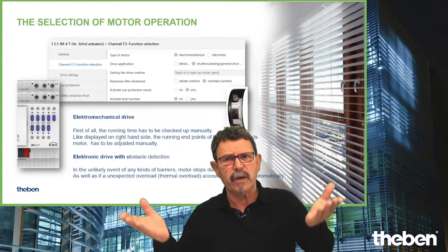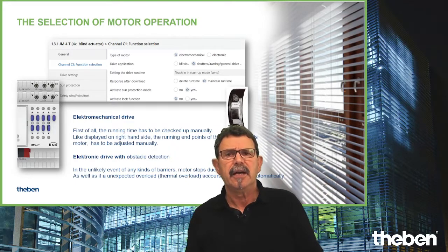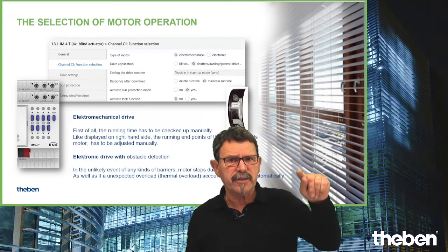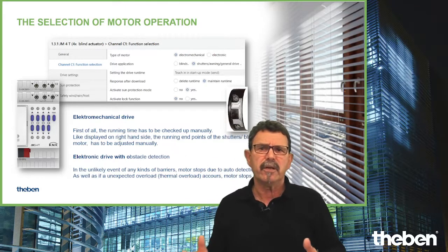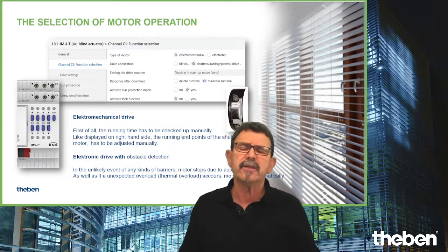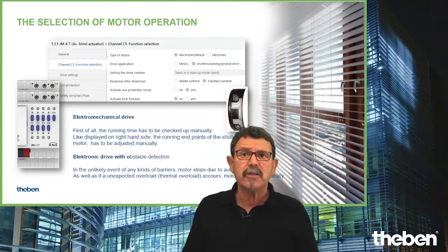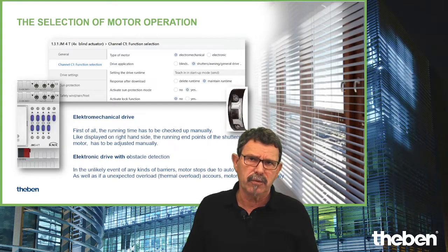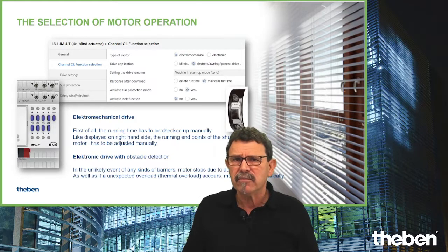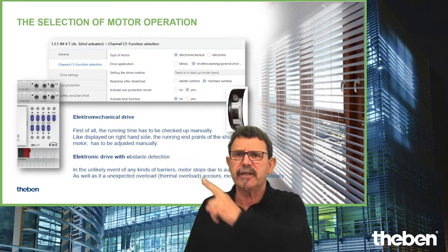And when it is rising in a teach-in mode and is finally at the upper position and pulling, then the current is increasing, and so the motor knows, okay, this is obviously my upper position. It's a quite smart solution, but you need to know that these electronic drives, these motors with the electronic circuit board, are rather costly in comparison to the electromechanical drives.